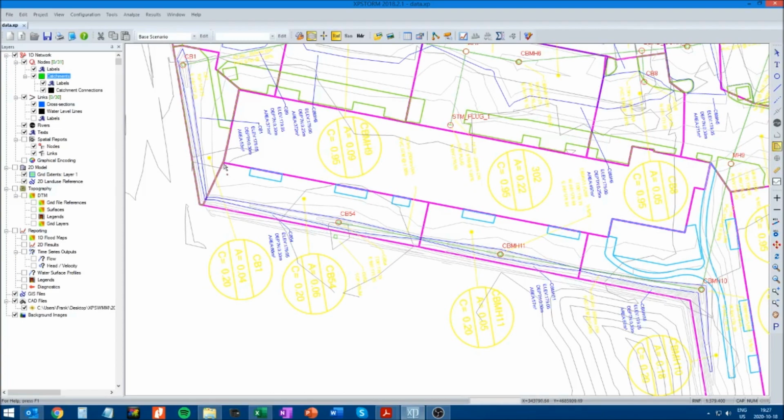and then we'll specify each corner of the catchment area. And hit escape. Sorry, you have to double click. Okay, and then the area sort of colors itself in. So at the end you have to double click, and that sort of closes the polygon. So for this one we'll go here, there.